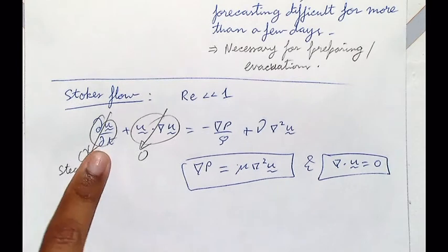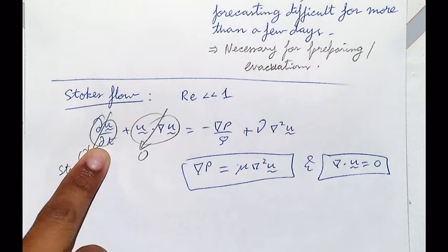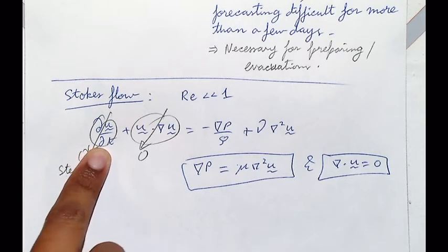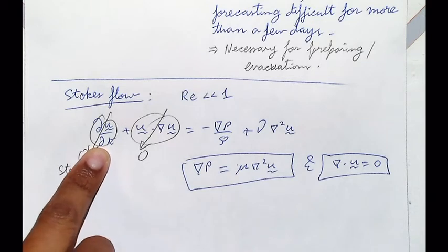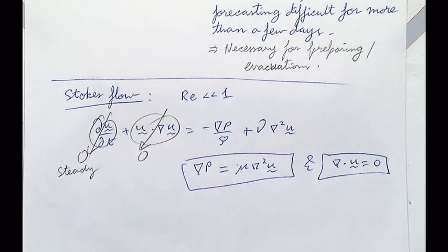Is there any change in velocity after the initial start? First of all, the initial start is one thing. Second, it was counter-rotating, right? So definitely there is an unsteadiness when it's counter-rotating. That's what I'm telling you. So, of course, you cannot start from something. Once it has started and you're not accelerating, you give me the u of the inner cylinder, I can give you the u from inner cylinder to outer cylinder, exactly. I don't need to know what happened 1 second before.